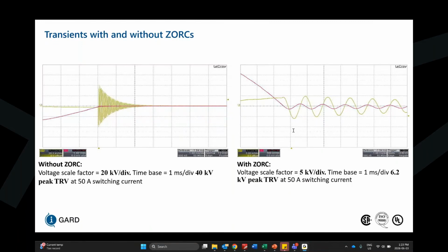Do you have any statistics for transformer failure rates when protected from switching transients by ZORC or RC snubbers versus no protection? I understand the savings versus a failure, but we have clients that are weighing first cost versus a theoretical future problem.